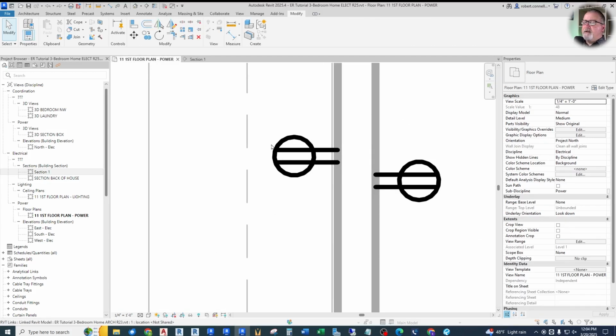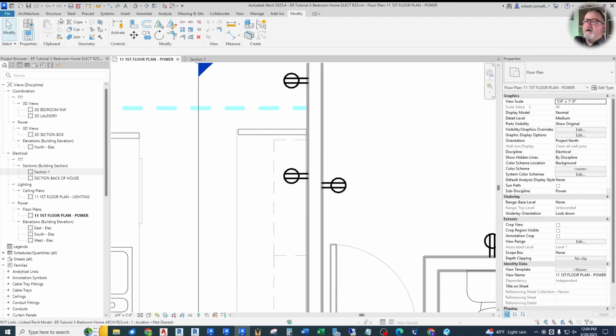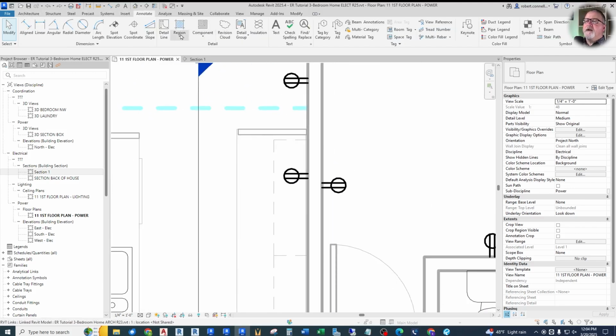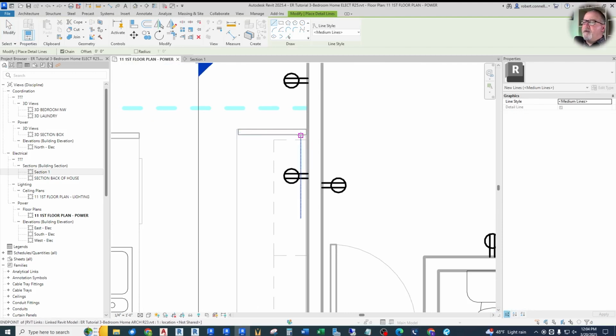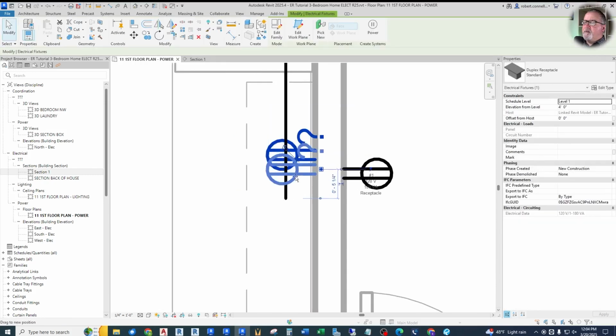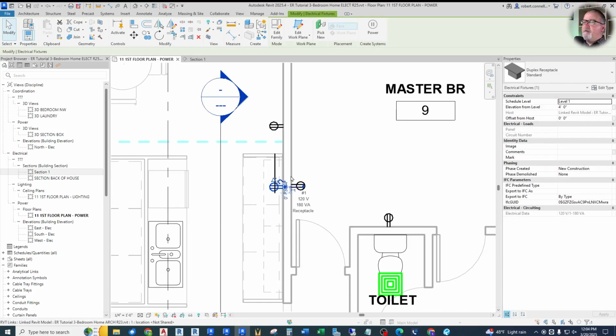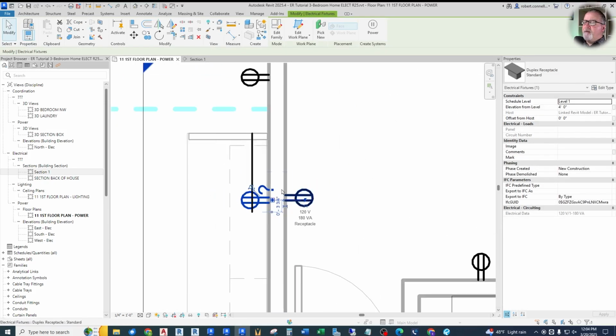So back here, let's take a look at how far away we are. So let's go to our annotate. And from the outside, the wall's underneath. So from the edge of this counter, I want to be within 2 feet. So there's the 2 feet mark. I'm going to pull this a little bit here. Now, you may worry about back-to-back boxes. Well, this one's down low, this one's high, so it may not be an issue.